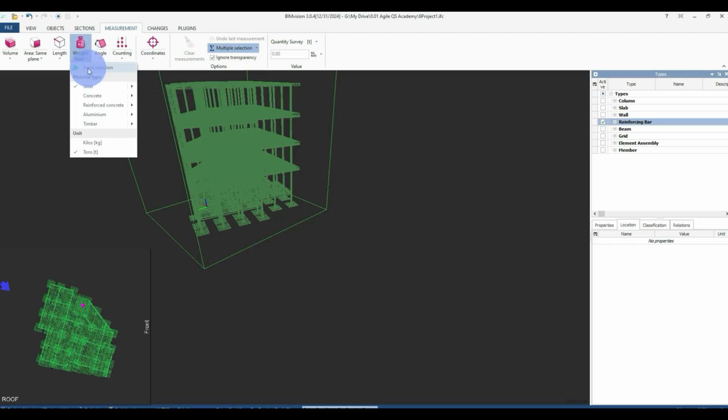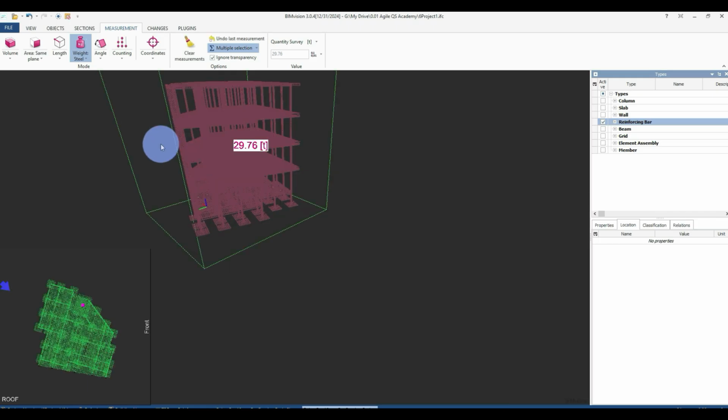So now you can go to from selection. Because now you confirm that it is steel which is picked, you can now click here, and after you click here, you are able to get the quantities, because it's now the steel which is selected. Then you select this, then you select from the model. If you pick from selection, it will take time, then it's giving you the tonnage of the reinforcements for the entire project, so 29.